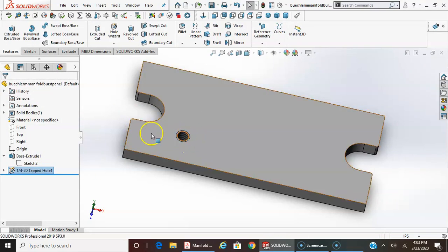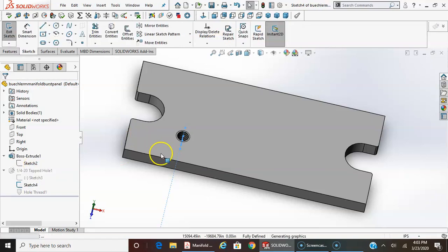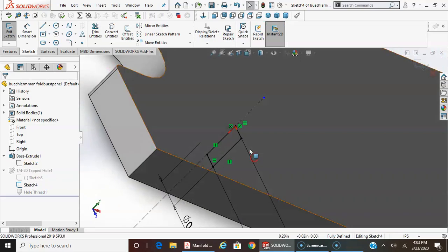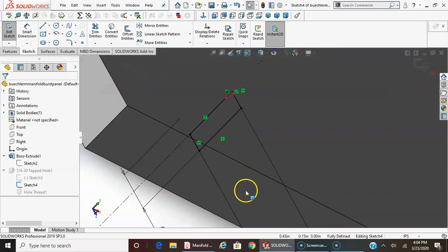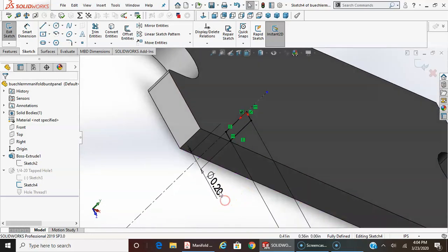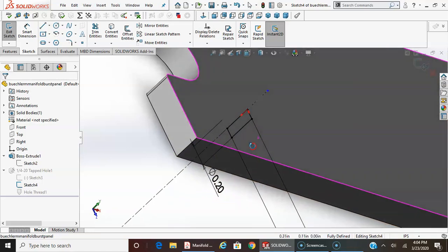And then it shows the hole, but I have to actually go back in, and there are 2 sketches in the hole wizard. There is the profile of the threaded hole. And in this case, it shows it fixed on the face I selected on the center. And this is going to be dimensioned right now. I'm going to show you. It shows a center line, and it shows a profile of the hole. In this case, it doesn't. It just shows, I believe, the minor diameter. Yeah, it's the minor diameter because this is a 201, which is our tap drill size for that hole.